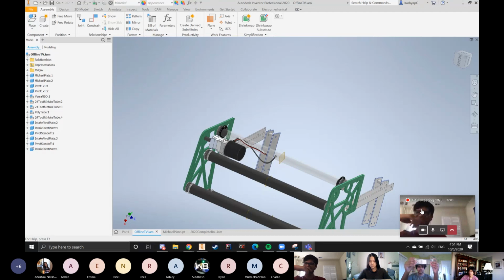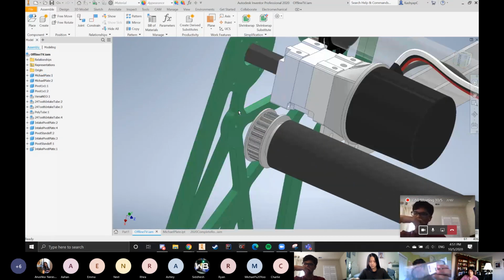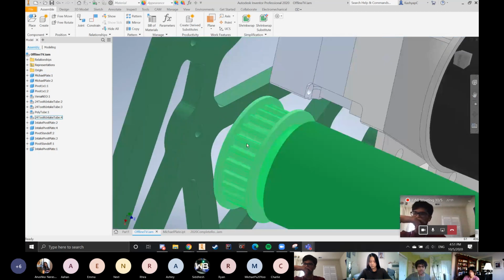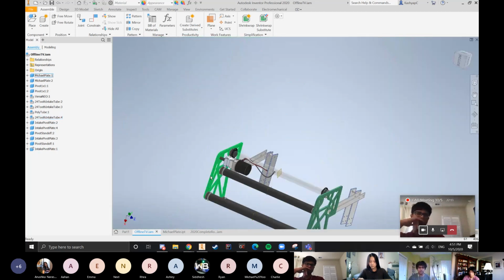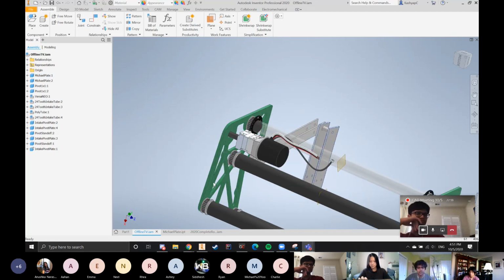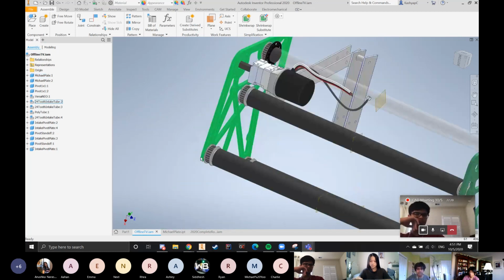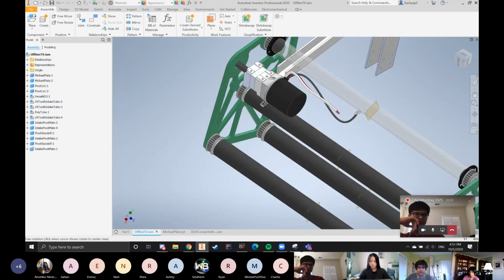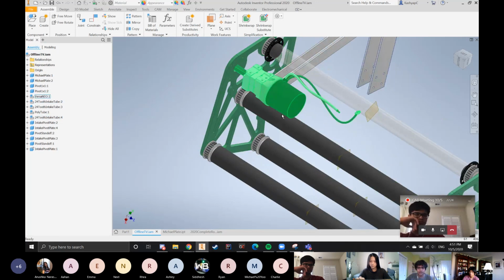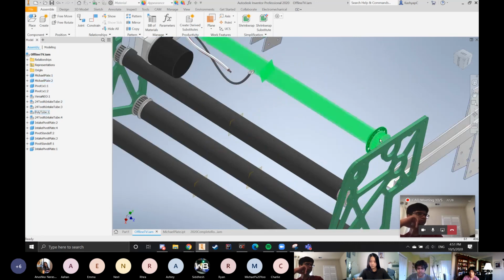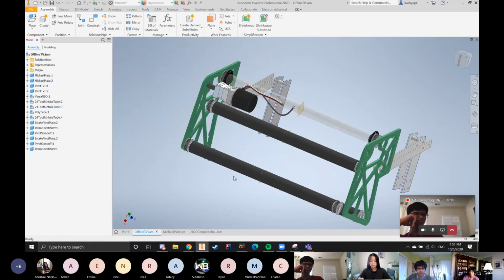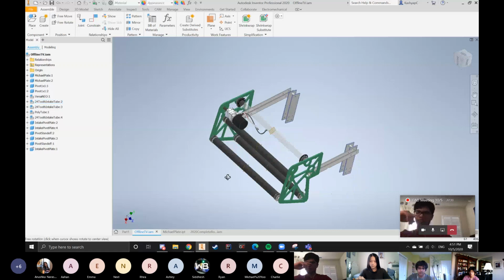But basically these little timing belts go from pulley to pulley, right? You can see that these also have teeth, and the timing belt engages on a timing pulley, just like how two gears would engage together. Not exactly the same, but they're pretty similar. What that allows us to do is have one belt from the motor here, which is mounted to the plate, all the way to this, and then from there to there, there to there, there to there.